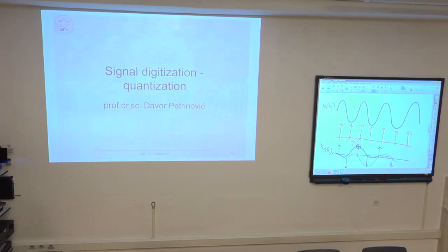It is like when you are at the market and you buy oranges, and then they have this analog weight, and then they put a 1 kilo weight on the left side, orange, it's not enough, half kilo, oh, then not enough, 1/4 of a kilo. It is a principle where this successive approximation AD conversion runs on that principle. So half of the scale is compared first, and then it is either higher than half of the scale or lower than half of the scale. Then you take another smaller weight, 1/4 of the scale.